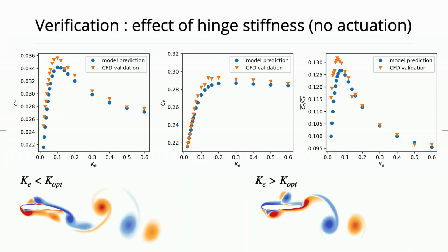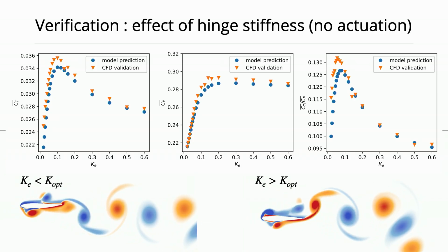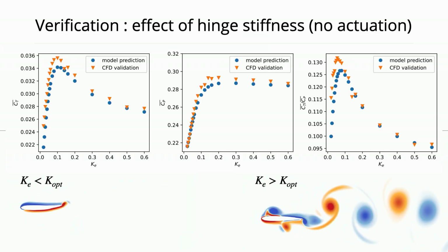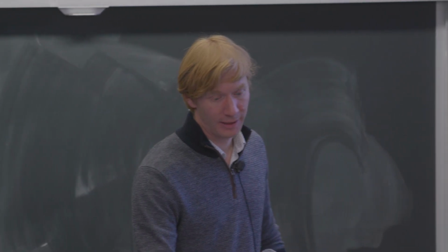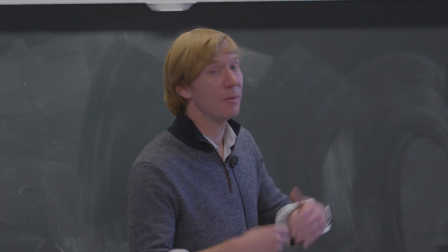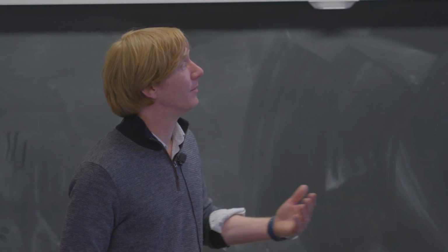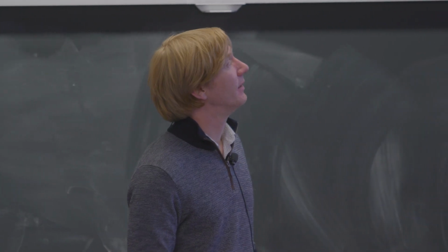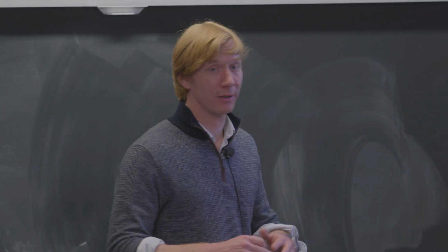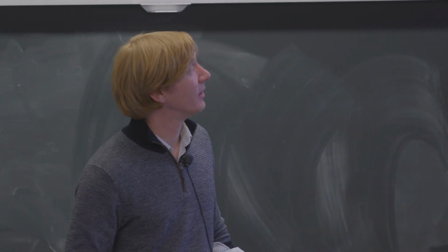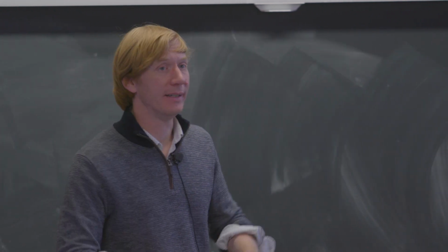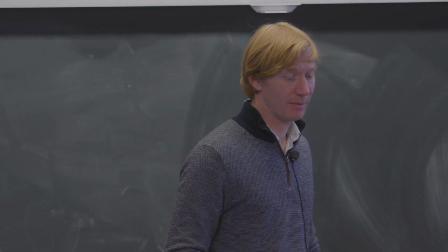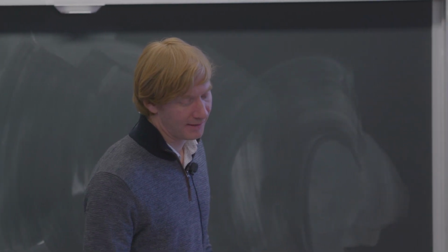And here are some examples of what happens if the spring is on the softer side and on the stiffer side. So with this model, we can run the fully multi-objective optimization without batting an eye, right? We can evaluate about 5 to 10 of these evaluations per minute. So in about 24 hours, we've done 10,000 parameter combinations, and we can run this in a simple genetic multi-objective optimization loop to optimize things.